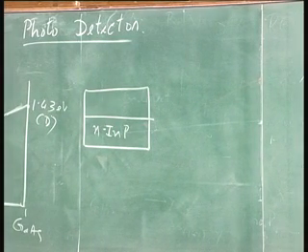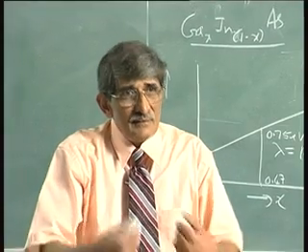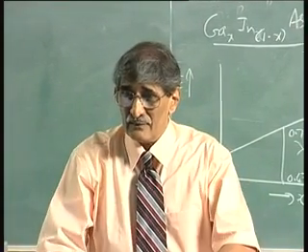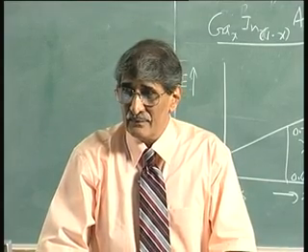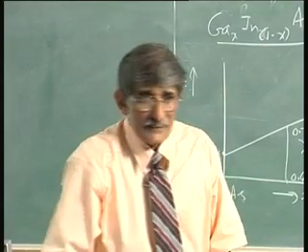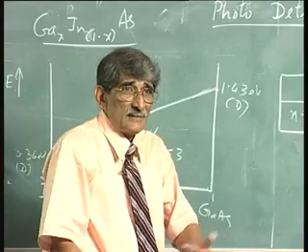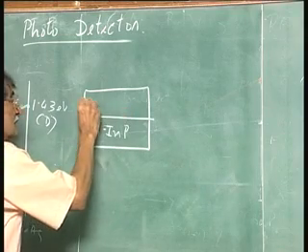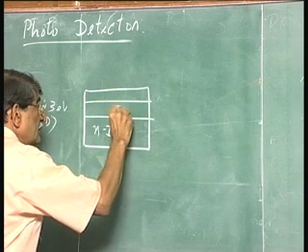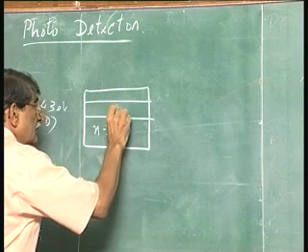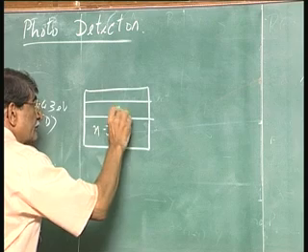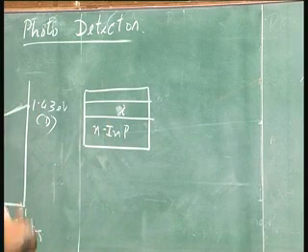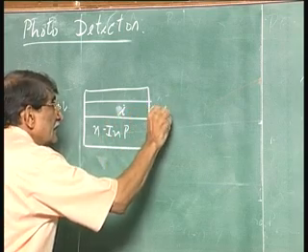In the LED, what you do? You forward bias it, force recombination, light emission. In the detector, light is falling, it is absorbed and you get the current. Electron holes are generated, you reverse bias it, you get the current, draw the current out, not forward bias. And here what you do is a new P type or I type, intrinsic or close to intrinsic,